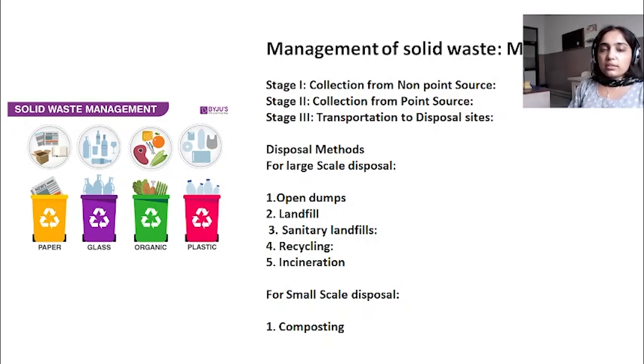So at first there are some stages which help in doing solid waste management. First are stages 1, 2 and 3. Stage 1 is collection from non-point source, that is when our workers are collecting the waste material from any point. But when a worker or any employee from the municipality or any government agency collects the waste material from a common point, that is collection from point source.